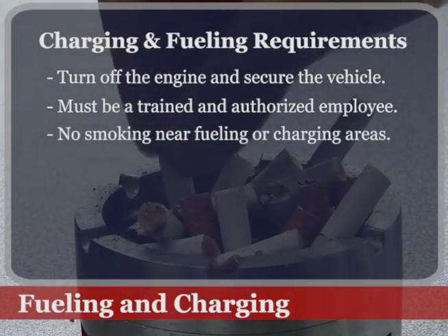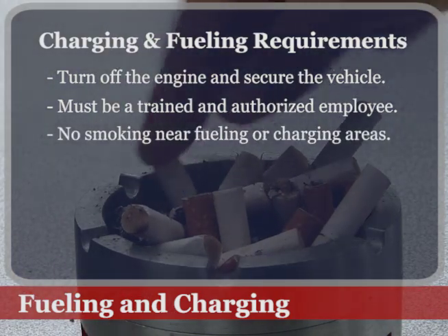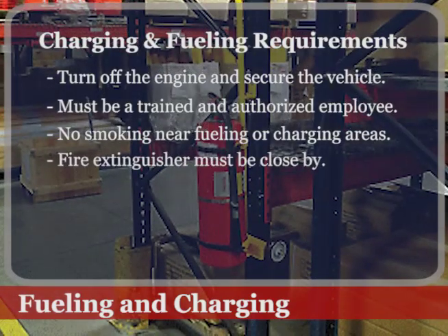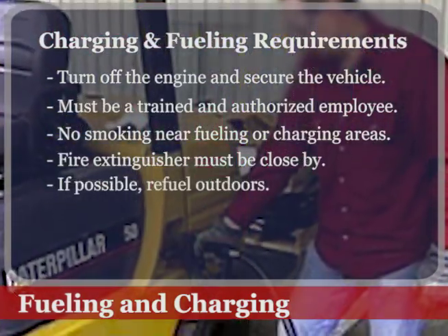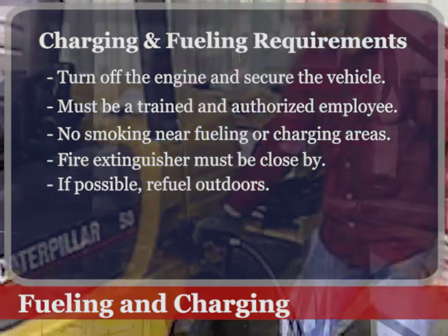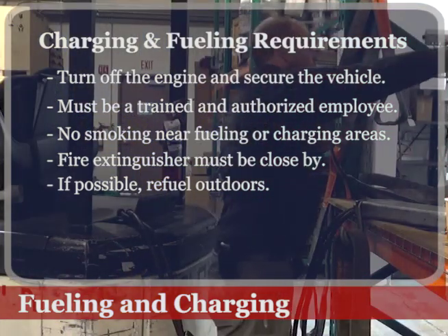Never smoke in, or near, a refueling area or a charging station. A fire extinguisher should be kept close by. If possible, refueling should be done outdoors. Indoor refueling areas should have adequate ventilation.